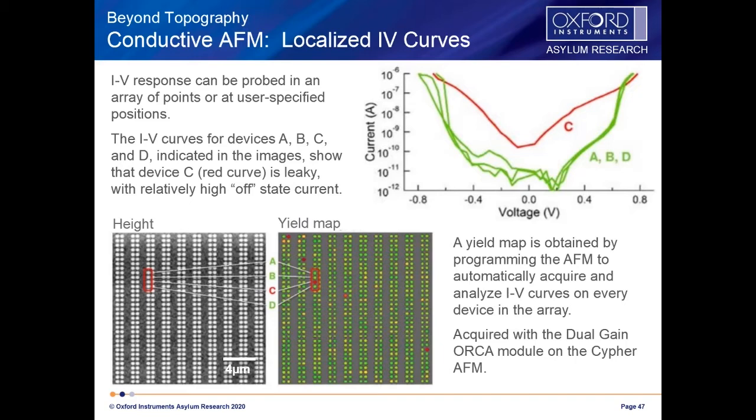And after taking this measurement, we can characterize the transistors into three types. One is an active device, the other could be a leaky device, another could be an open device. And we can assign a color code to these devices. So an active device is something that has a regular profile in the IV map. Those are characterized as green in the yield map.